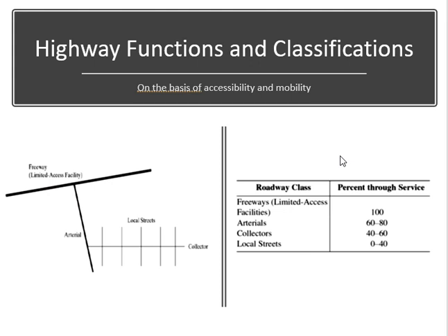We have the freeway connected to the arterial connected to collectors. They are only showing one collector, but arterials can be connected to multiple collectors. It's an intersection, basically. And then one collector is connected to multiple local streets. Now you may say each local street has just one connection. No. It has one connection with a collector, but each local street is connecting each house and each shop and each facility on the street. So when you come out of your garage, you are on a local street.